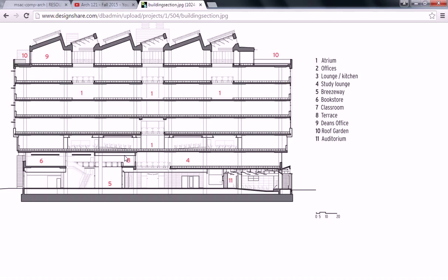Usually these are illustrative, and the reason an architect would do a drawing like this is because then you can draw a little bubble around this area and say go to that at a larger scale. So you go to a page later on in the drawing set and it blows up and you can see a lot more detail. That's the way these drawings typically go. Even with floor plans, you go from a floor plan down to an enlarged plan where you can see some more accessories and where they're located. Then you can go even further down and you can see the actual construction of the wall, right?